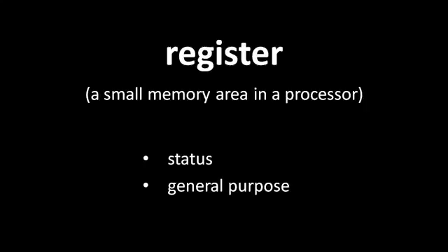Well, most CPUs can only perform operations on data in the registers, not in memory. Addition instructions, for instance, generally can only add numbers in the registers, not numbers out in the system memory. So to add two numbers in memory, we must first copy them to separate registers, and the result of the addition operation gets written to a third register, from which we may then copy the result out to memory if we wish.